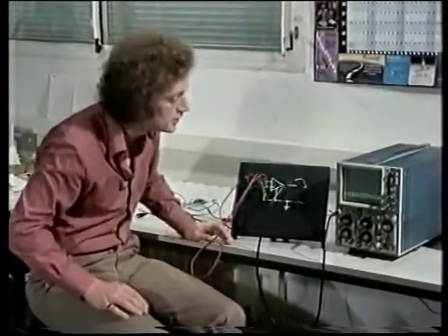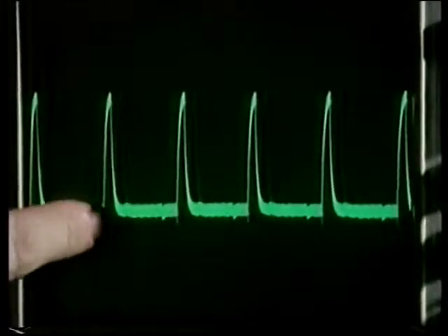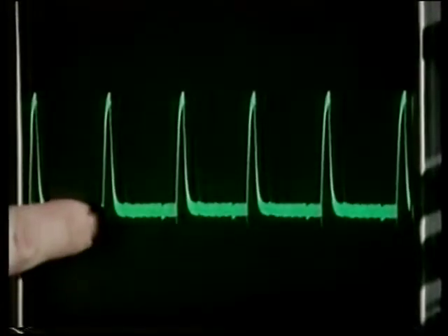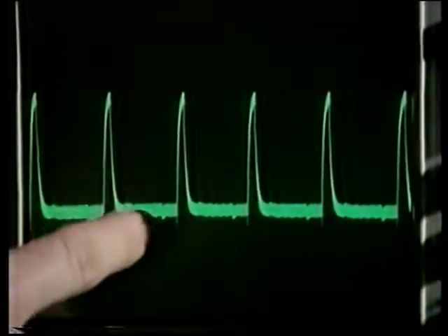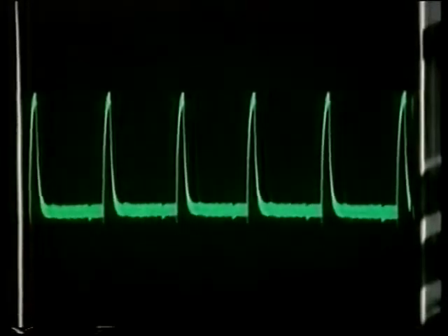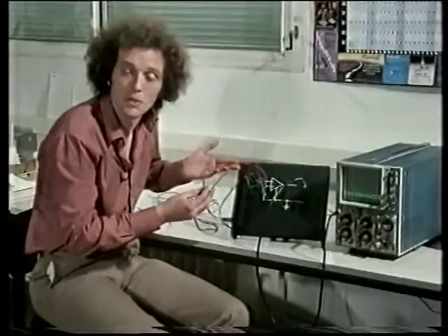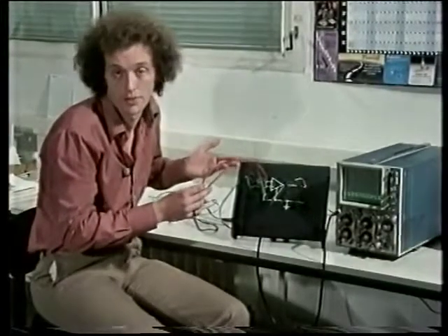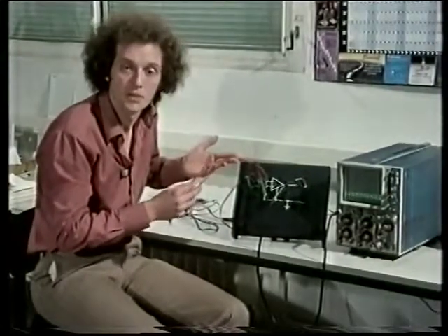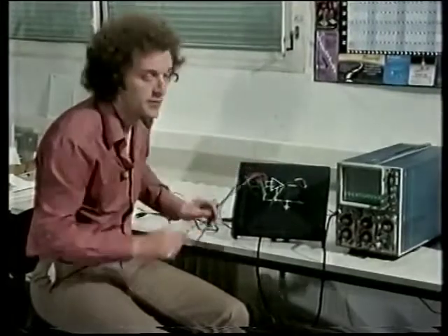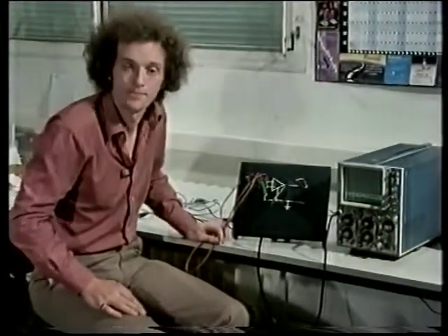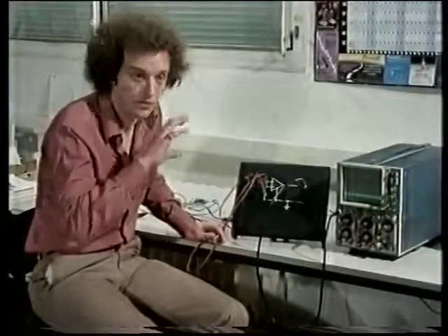And what we can see on the scope is sharp pulses which simulate the signal, and the jittering that we can see is the pickup that we've induced. Now, these leads represent what could be quite long leads between the patient and the monitor equipment. So pickup is obviously a problem. Now, we've got a differential amplifier, so why not use it? Let's connect it in a differential mode.